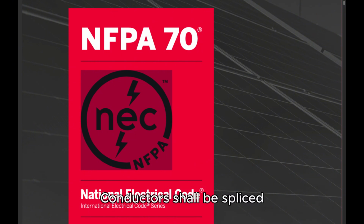B. Splices. Conductors shall be spliced or joined with splicing devices identified for the use or by brazing, welding, or soldering with a fusible metal or alloy. Soldered splices shall first be spliced or joined so as to be mechanically and electrically secure without solder and then be soldered. All splices and joints and the free ends of conductors shall be covered with an insulation equivalent to that of the conductors or with an identified insulating device. Wire connectors or splicing means installed on conductors for direct burial shall be listed for such use.